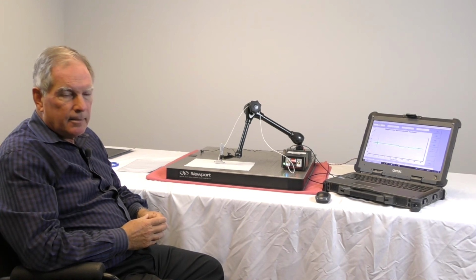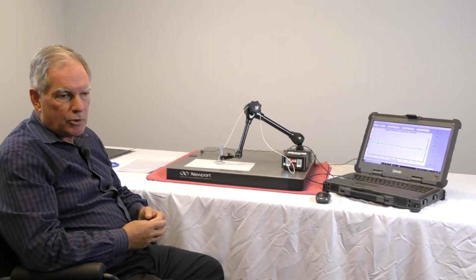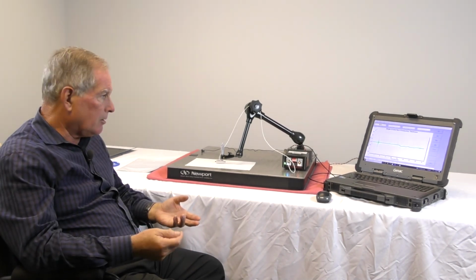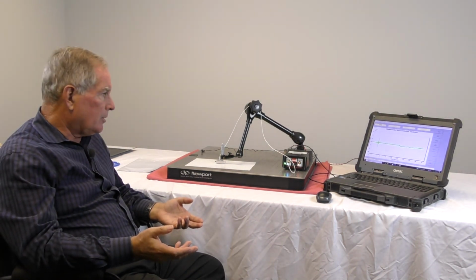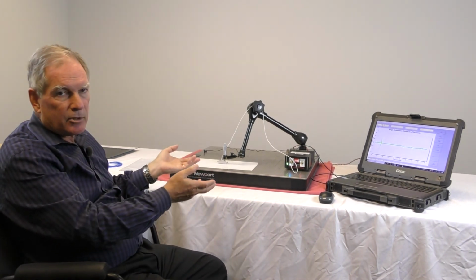We'll also add that we're going to have a slide in here on how to measure density of materials too. So we can measure thickness if you know the thickness. If you don't know the thickness and you're concerned about measuring the density of materials, which is a large measurement that people want to make, what you would do is there's a specific mathematical algorithm that relates the density of a material to the thickness of the material and the dielectric constant, or the capacitance. In this case, we're measuring the capacitance, really.